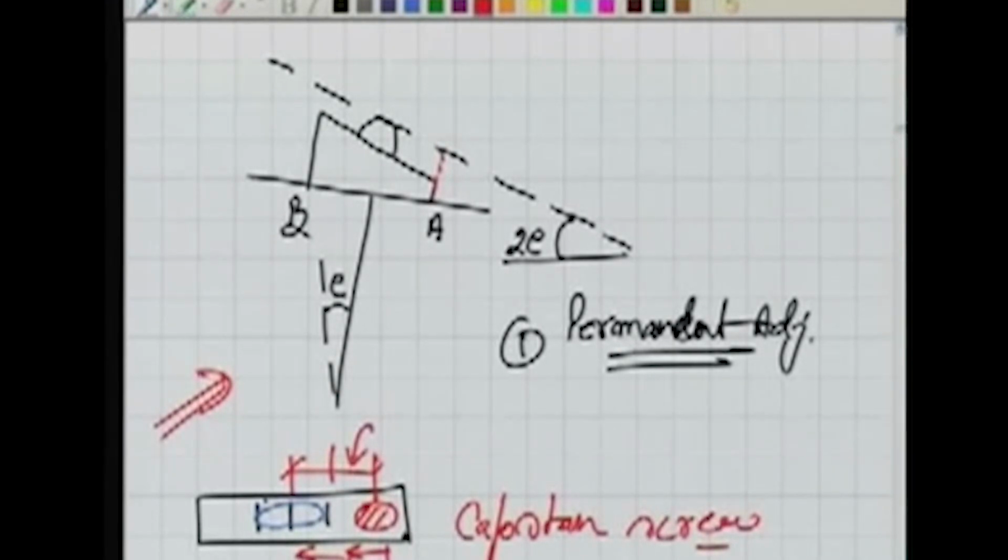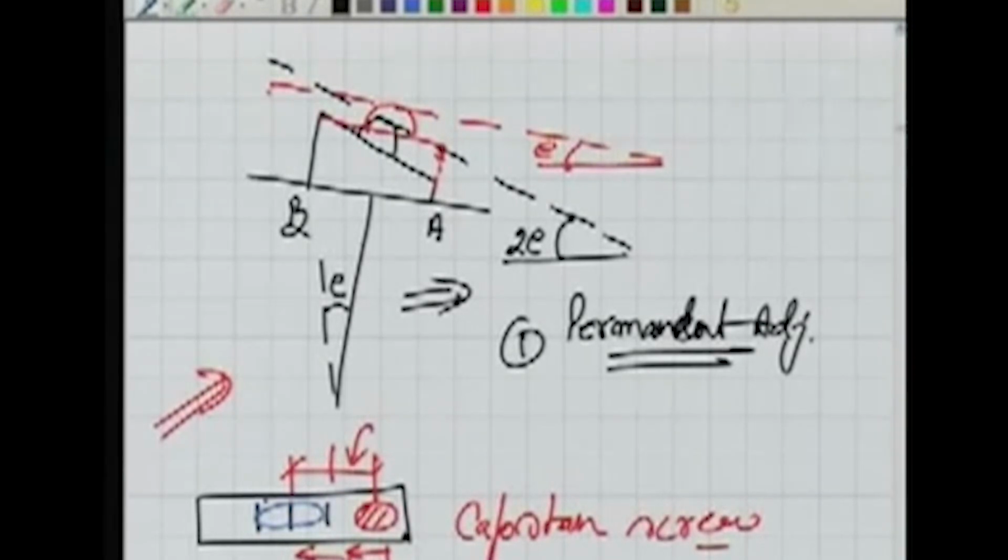So my bubble becomes like this, and the line of sight and the axis of the bubble tube is now this way. Now this angle will be obviously E. So half of the error has been eliminated. Next, if I further now change or bring the bubble to center using the foot screw. So when we are using the foot screw, basically what we are doing, we are changing the orientation of this vertical axis. So what we do in this case,